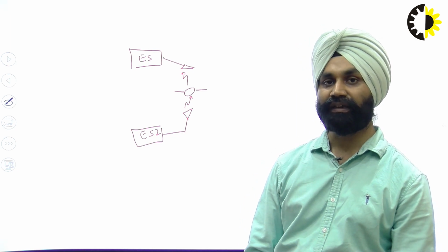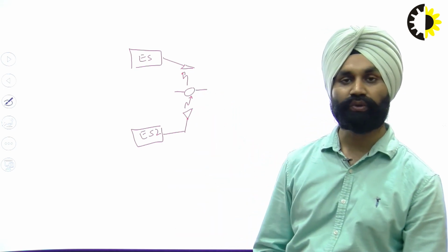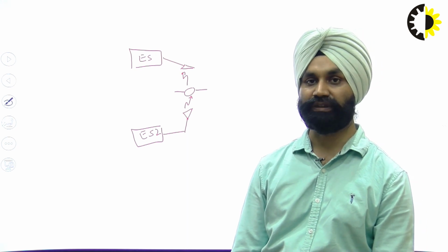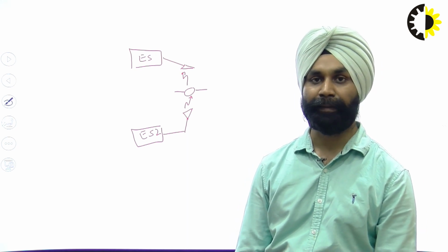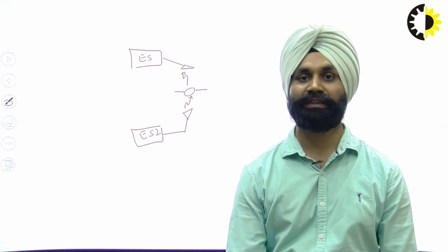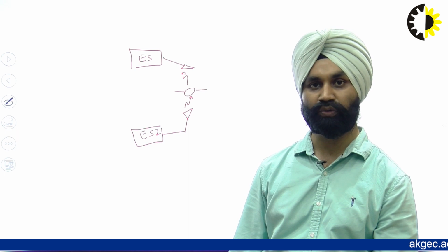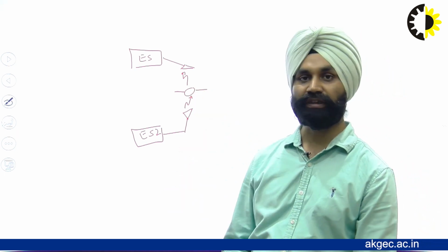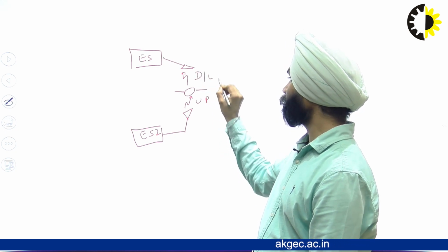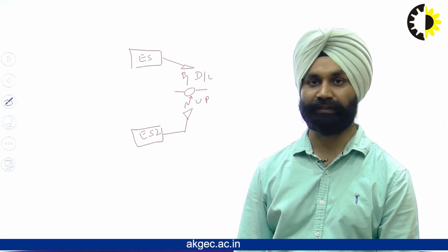Now consider the case when the transmitting and receiving antennas are nearby, for example on this satellite, the transmitter and receiver antennas are both very near to each other and both are transmitting and receiving. So we must have something that differentiates between the input signal and the output signal. To differentiate these two signals, one is the uplink signal and the other is the downlink signal. Both signals have different frequencies and both are polarized.